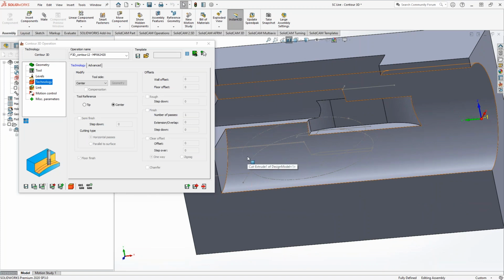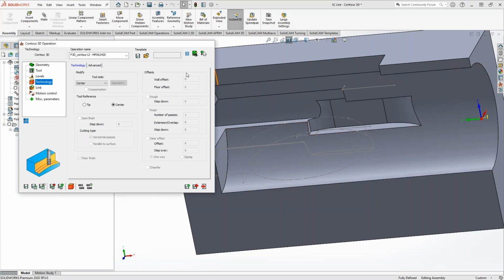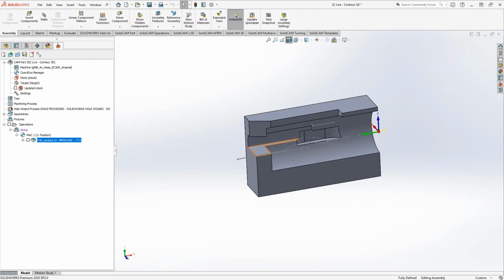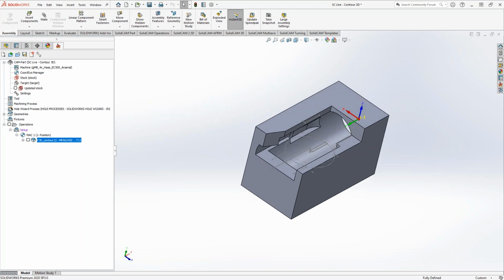So there's a lot of internal workings that when you do the sketching and you look at your part, you can figure out trajectory. But it goes back to what I was talking about. You can actually add a bunch of geometries, some sketching and whatnot that can really help you in your programming, because when I came here, I literally just chose the chain and that was it. I didn't have to do any extra programming. Everything was done on the sketch side of things, the geometry side of things.